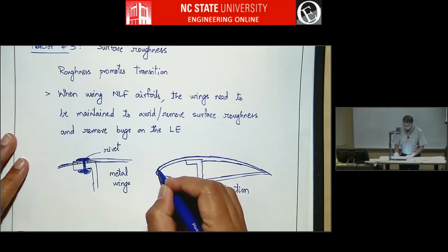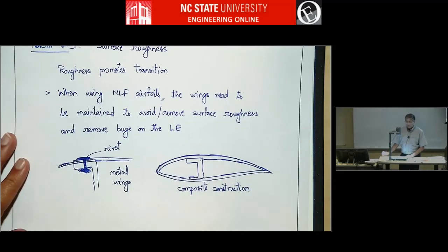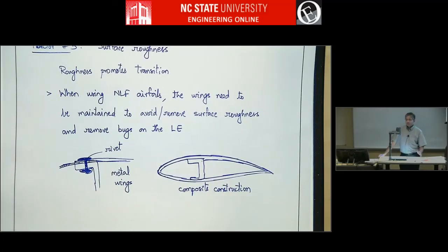accretion of bugs and some debris in the leading edge, which will cause transition. So on these kind of airplanes, if you want the benefit of laminar flow, people actually go and clean the leading edge every so often, especially if it's a competition sailplane. I mean, this laminar flow matters a big deal because they're usually competing with each other, and even a small increase in performance matters.